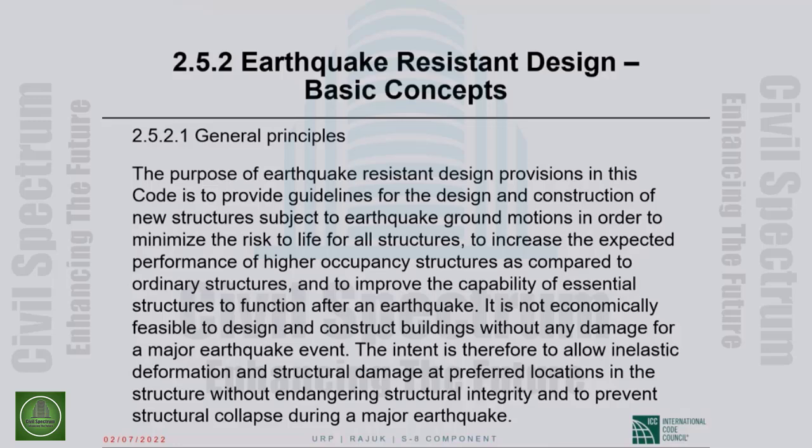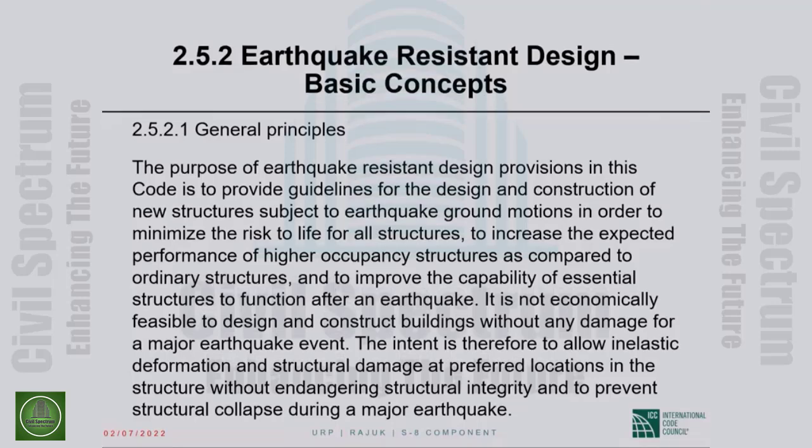We deliberately allow inelastic deformations at selected locations under the design earthquake, but we have to make sure that the inelastic deformations are within inelastic deformation capacities so that we do not have collapse. We do not have problems with structural integrity.